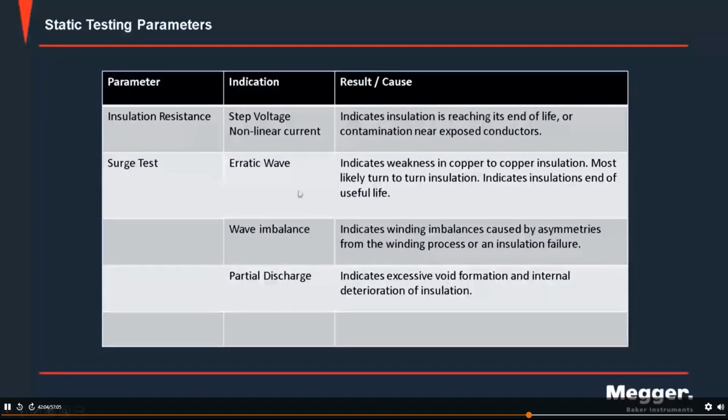Surge testing, we're basically impulsing some energy on the winding, and we're looking at how that winding is responding to that energy. This kind of ringing is almost like a resonance test, if you will, like ringing a bell. We're looking at, are there any cracks in our bell? In this case, are there insulation weaknesses that the surge test can identify? And that's specifically looking at the turn-to-turn insulation that we talked about at the beginning of the presentation.